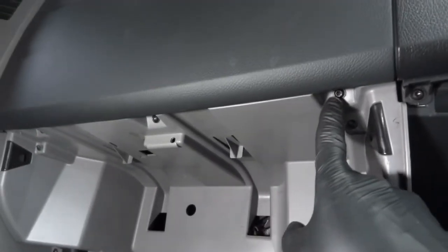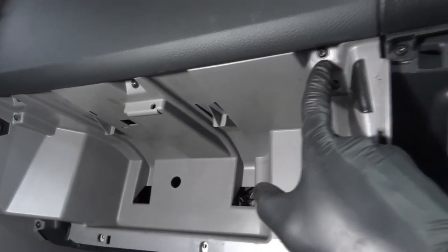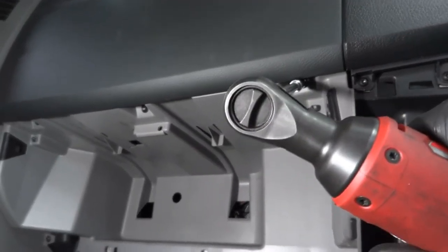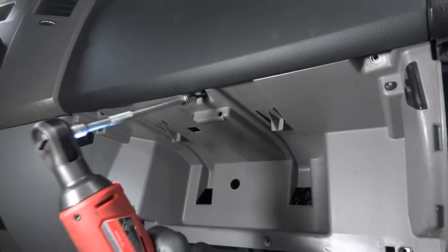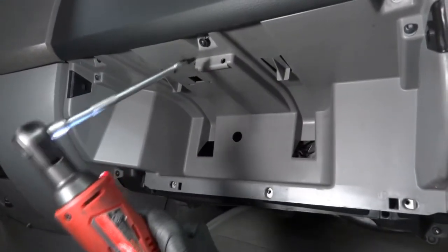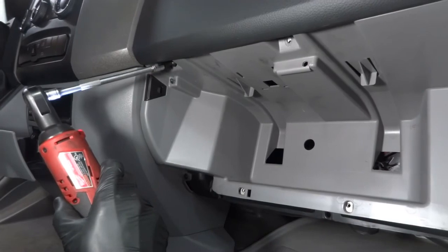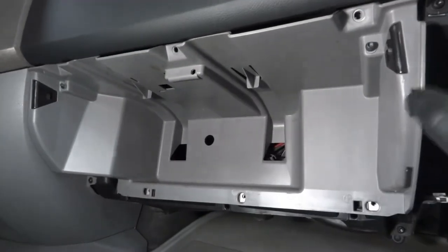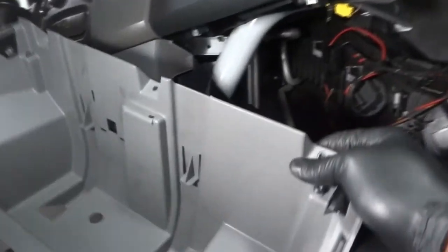We have to remove these 3 T25 torque bolts. So there's this one, that one, and this one over here. Once we undo all of these 3, this cover is gonna come off. And once we remove this, we'll get access to the blower motor. Okay, so this one comes out. Now we're gonna undo this one. Now we're gonna undo that one over there. Alrighty, so this plastic cover here should come off. Okay, perfect. So I'm just gonna sit this over here,